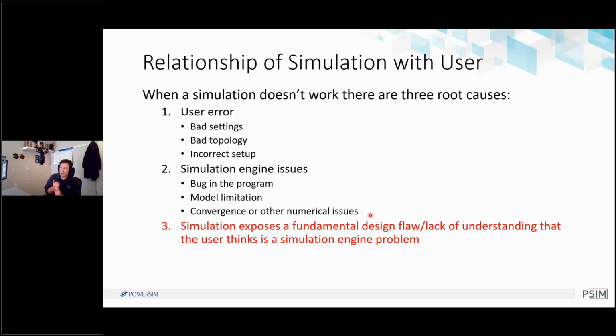Whenever you turn a switch on or off, you introduce a derivative in the voltage and current. With state-space matrices, you can have issues where those matrices won't converge anymore. They won't solve. So you need to take a really small time step in between, and that can lead to issues in the state-space matrix approach when there are lots of switches going on.